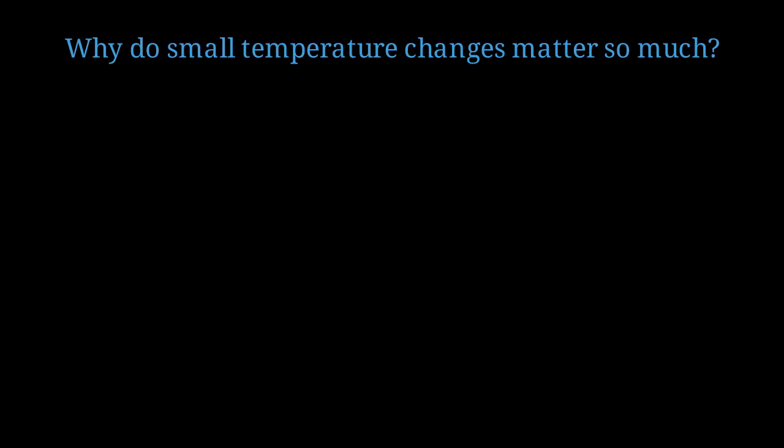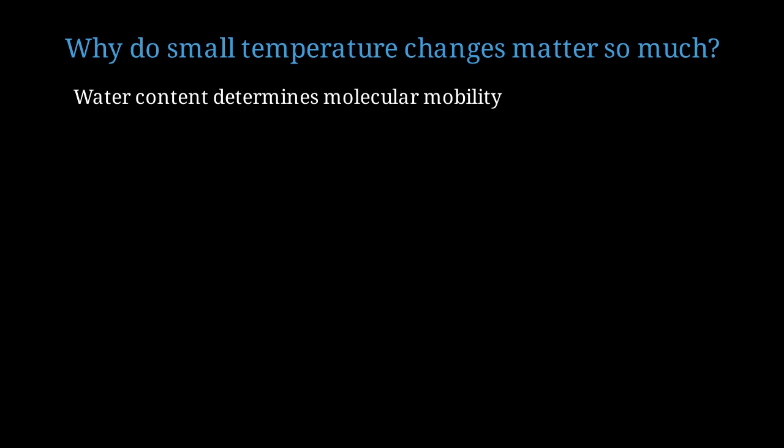You might wonder, why does the difference of just a few degrees Celsius completely change the candy's properties? This is where thermodynamics and materials science converge. The answer lies in water content. Each degree of temperature increase corresponds to a specific amount of water evaporation. Even 1 or 2% difference in water content drastically affects molecular mobility.